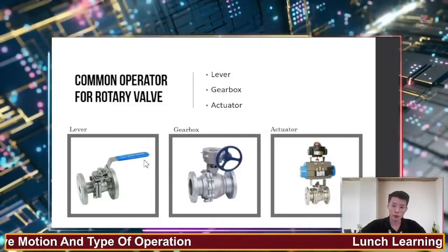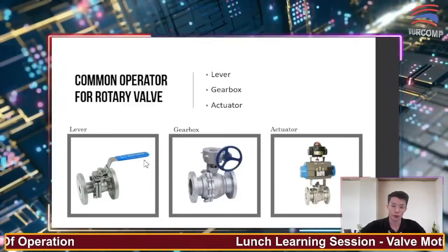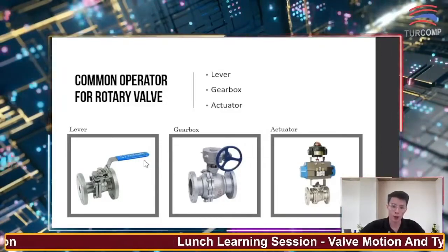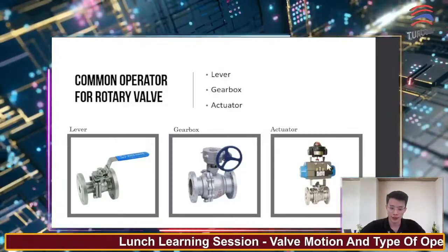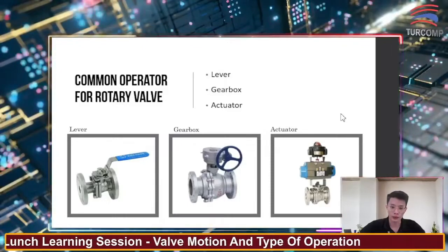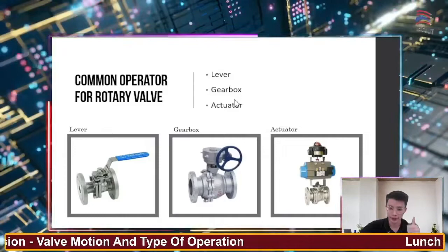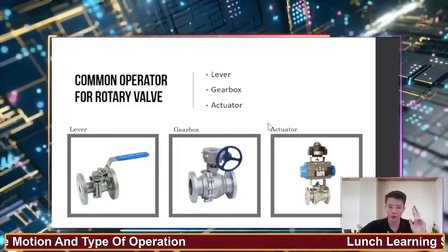However, when the valve size is getting bigger, we might need a gearbox to reduce the input torque required to operate the valve. Similarly, when we want to control the valve open or close, we can use an actuator, which can be pneumatic, hydraulic, or even electrical type.